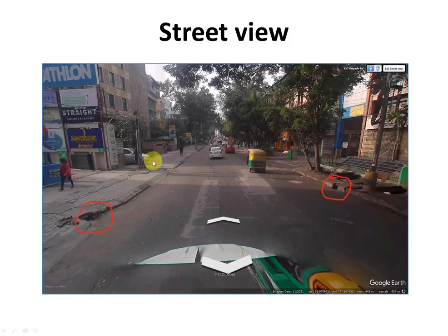This is the location where I mentioned the flooding is happening, near the Patrick Church, near Brigade Road. There are two vents here, which you can see where I marked, near the road curb. This is where the flooding occurs, because these are located at the road sag point. All the road runoff and land runoff from the surrounding area directly discharges into the street, and it doesn't have any proper drainage system here.